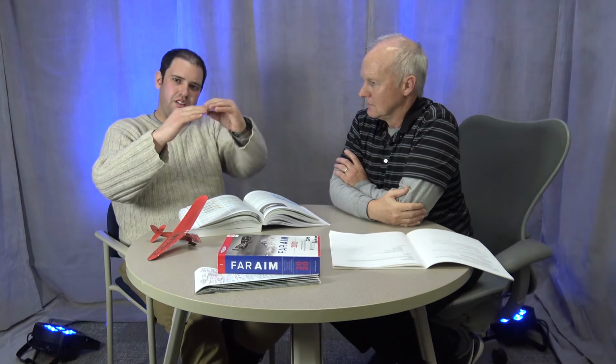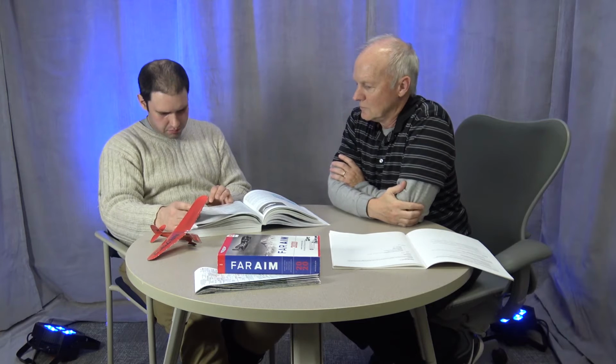They go way down. They go off the leading edge of the wing down to create what that essentially does, which is it reduces the angle of attack at the leading edge of the wing even more, in combination with the flap at the trailing edge, increasing the angle of attack at the back. Basically turns into a big scoop, so that as the angle of attack increases, it just doesn't want to stall. Creates a bigger undercamber on your wing to make it float better. Yep, and you get more lift at a slower speed.